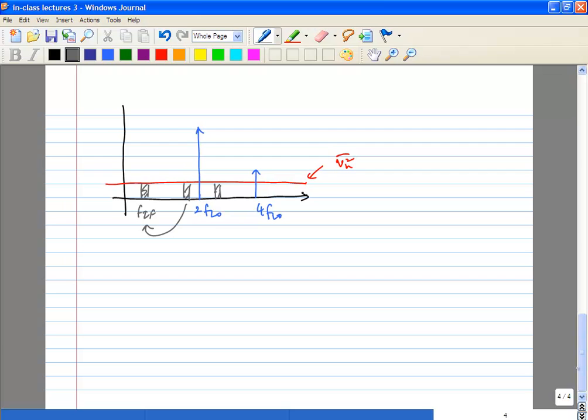So you have noise from here, and so on. But obviously at a certain point you have to stop. What is that point? If you look at the pulse train which is sampling your noise, with this TS, what does it look like in the frequency domain? It looks like a sinc function, right? That's at 1 over TS.